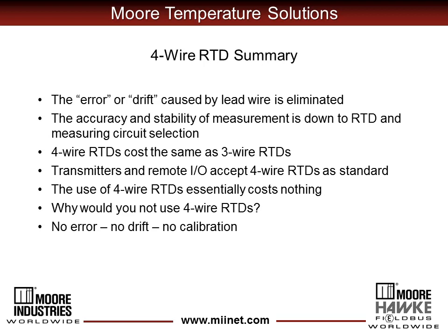With your lead wire error gone, you can go back to focusing on selecting the right sensor and selecting the right measuring device to further eliminate error sources.